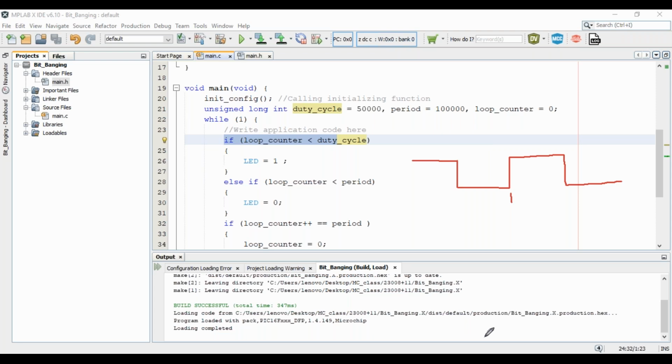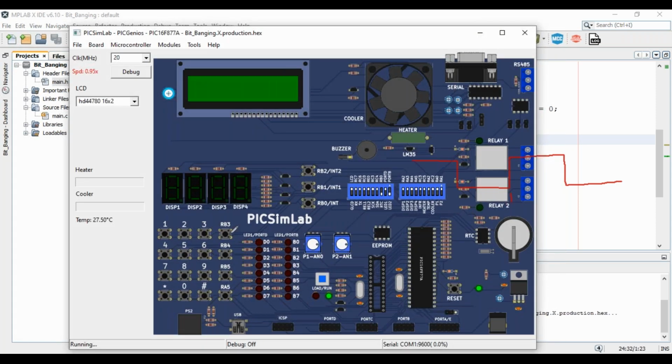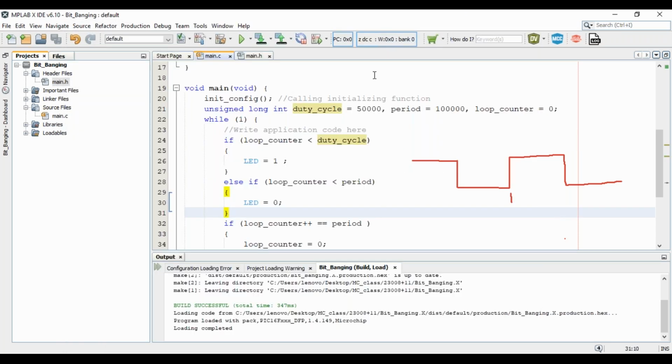So that is why as of now you are able to see the toggling of LED. But if I reduce the period and increase the frequency, I will not be able to see the toggling of LED, because LED will feel as if there is continuous smaller voltage being provided to it. So that is why LED was glowing with a small amount of brightness earlier.